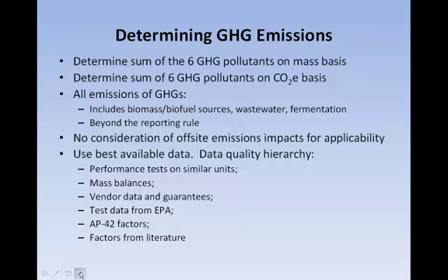Emissions analysis under PSD goes beyond what is required to comply with the reporting rule, that is, the mandatory reporting rule. For example, biogenic sources that are not covered by the mandatory reporting rule must still be determined. These include the use of biofuels, the emissions from landfills, wastewater systems, and fermentation processes. Also, there are no de minimis size thresholds for any types of sources under PSD. Also, when determining PSD applicability, there is no consideration of off-site emission impacts on GHG emissions.